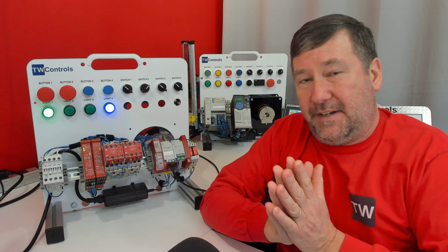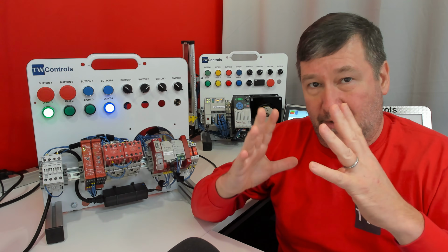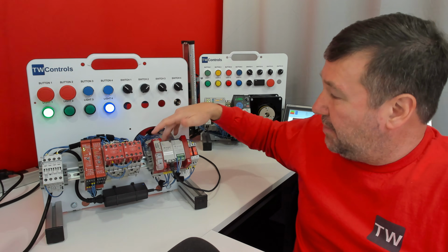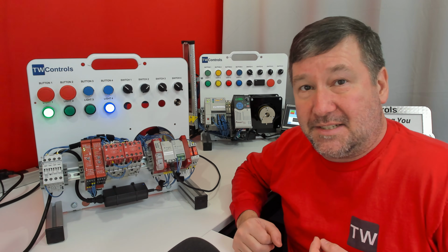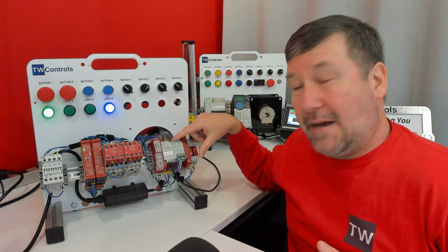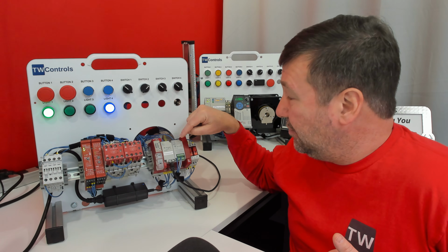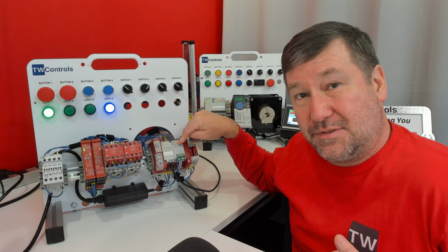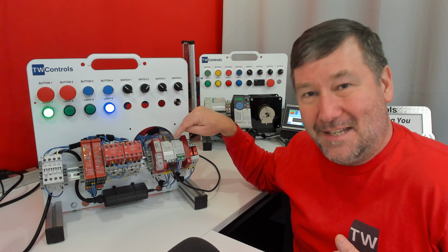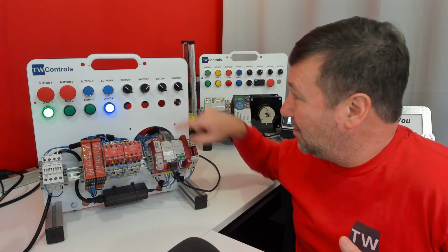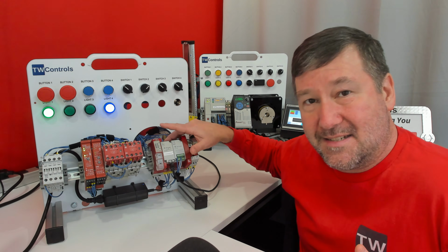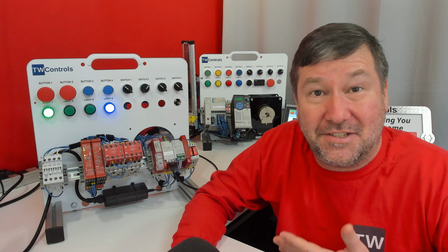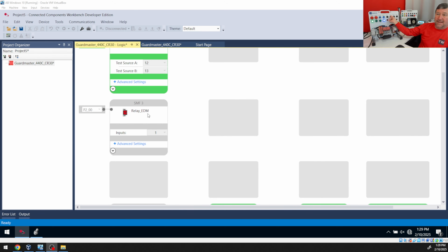P2_00. If it is actually a safety output or a safety input, it does have to be on the CR30. Now, the feedback circuit can be on a regular input. So P2 means plug-in module 2, 00 is input 0. So we are actually taking our reset to our plug-in module. We could take it to this too, just mainly showing you different things you could see.